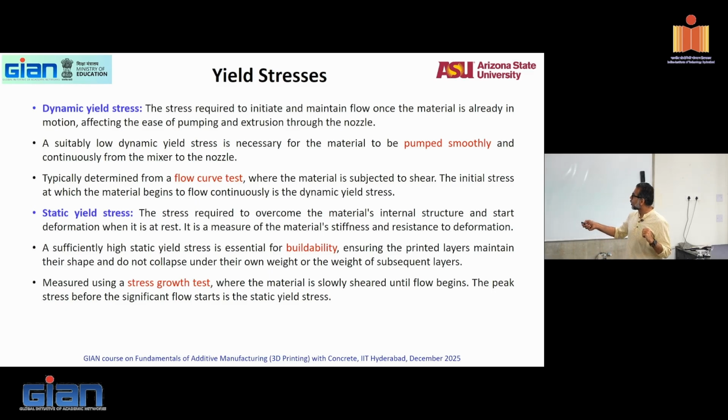that is a stress that you find to maintain flow. A suitably low dynamic yield stress is required to be pumped smoothly through the mix. So pumping requires a suitably low dynamic yield stress. Building up requires a suitably high static yield stress. And static yield stress, so a stress growth test where the material is slowly sheared until flow begins. You measure the static yield stress, and a flow curve test where you do the strain rate ramping up measures